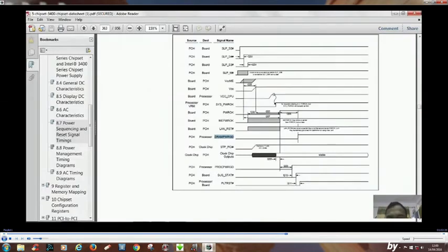And what is the next signal? After the PCH indicates to the processor that the RAM power supply is okay, and all the other voltage power okay indications have been done, that is power okay, ME power okay, LAN reset, these all have been indicated to the PCH.